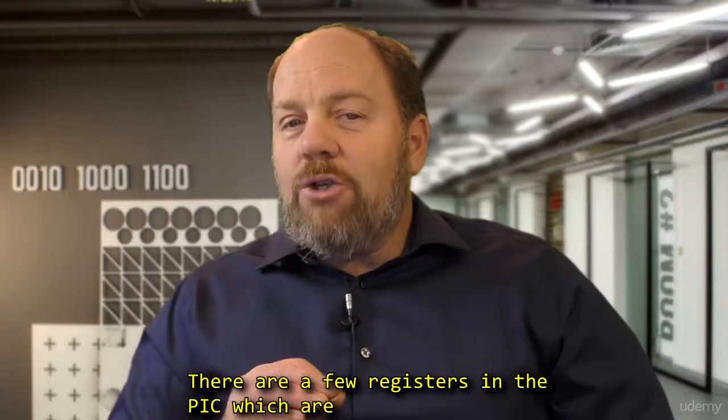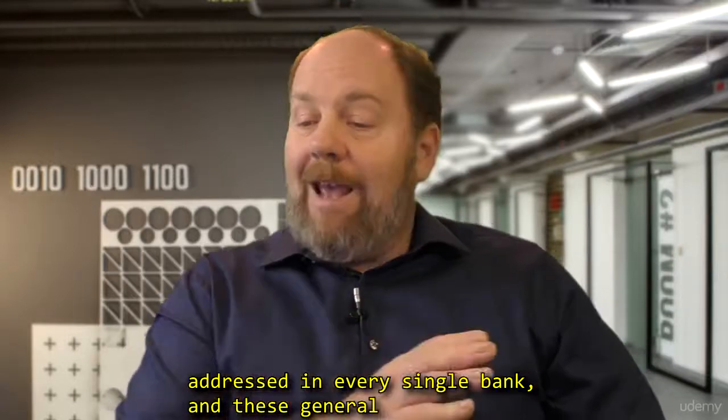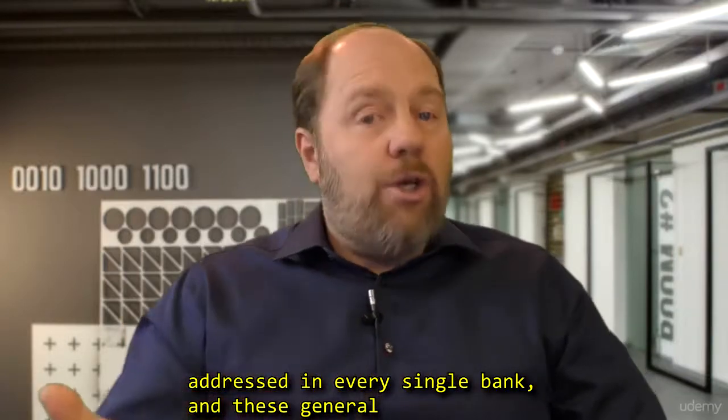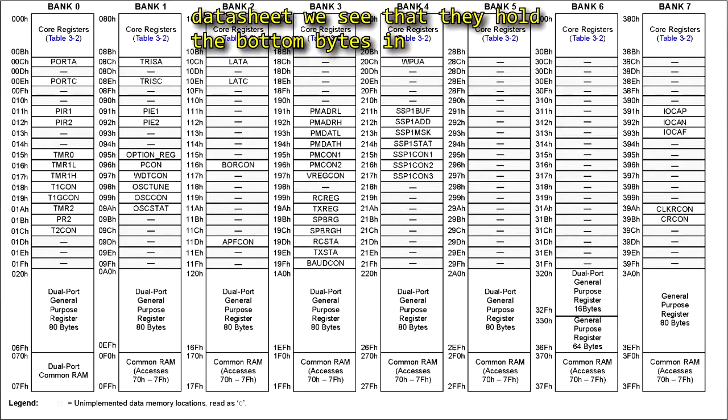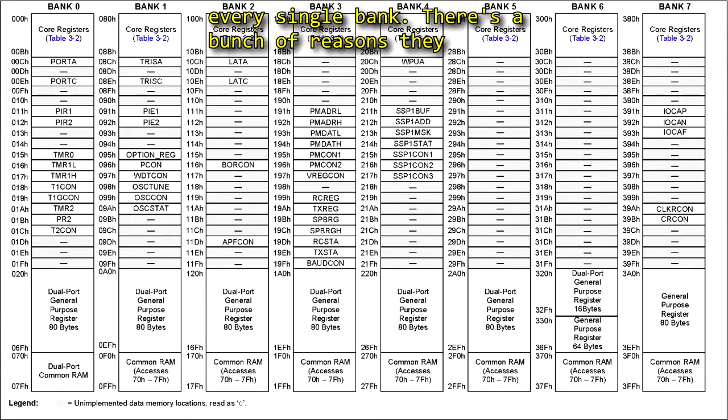There are a few registers in the PIC which are addressed in every single bank, and these general purpose RAM locations are some of them. Now here in the data sheet, we see that they hold the bottom bytes in every single bank. There's a bunch of reasons they did it this way, but for now, just go with the flow.